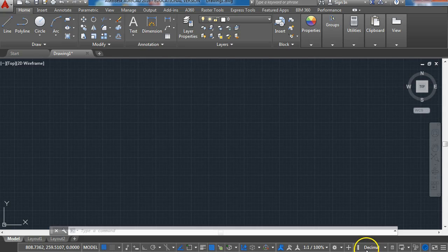Okay. So to kick off drawing with a basic line, we can go to the line tool here. Click on that once. It comes up in our command prompts. This is perhaps our most important part of the screen. This is the brain of this program. It tells you what's happening, and it asks you and tells you what to do. So we have a line. This is telling us it's our line tool that we're in, and it's asking us to specify our first point.